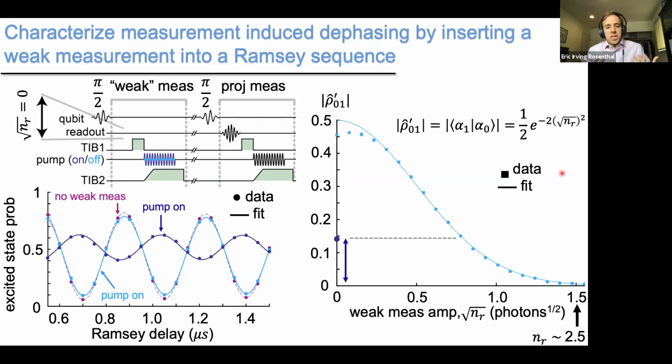If you like to think of isolation in dB instead of in photons, from a different measurement, we find about 150 photons in the pumped parametric amplifier. And so our 0.6 photons of back action corresponds to about 25 dB of isolation. And that's a little bit better than one commercial ferrite. Usually we use maybe 3 ferrite circulators. But this 0.6 photons, we're maybe sad that it's not a little bit closer to 0, but it's still only about 1/4 of the photons that we're using in our projective measurement. So when we make this projective measurement, most of the back action of our measurement is caused by this readout pulse we specify, not by some back action from the detector.